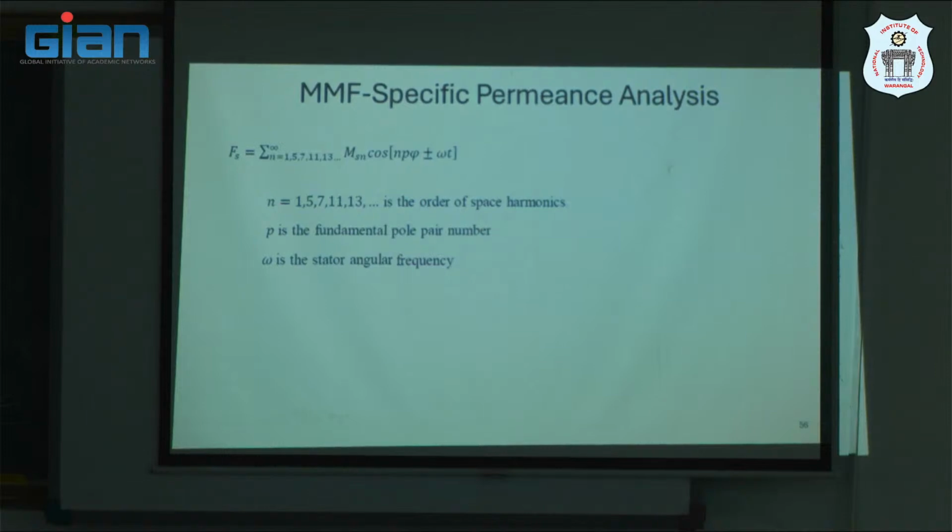So first thing is the stator MMF. Now, stator MMF in electrical engineering, we always start with a very typical assumption that the winding is sinusoidally distributed, right? But we know for a fact that it is not true. We cannot manufacture such a machine, or it becomes very intense to manufacture such a machine. So when we actually use a practical three-phase stator winding, the winding distribution will result in what is known as space harmonics. How many of you have heard of space harmonics?